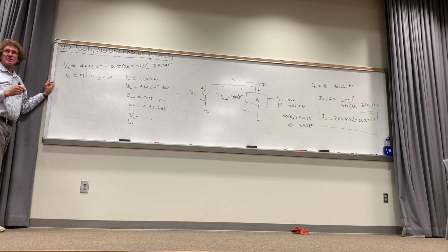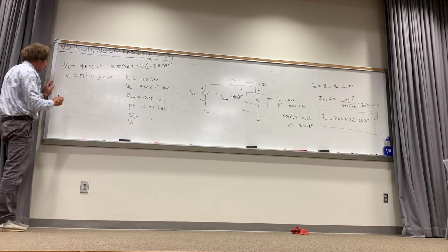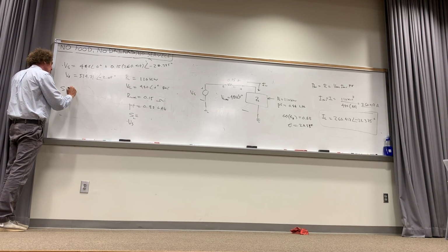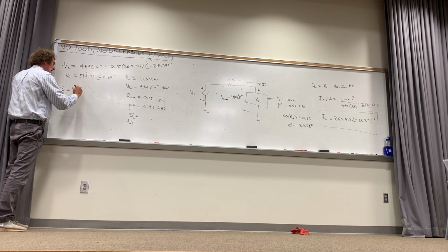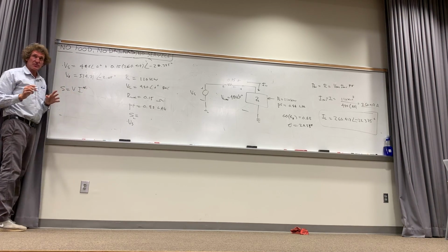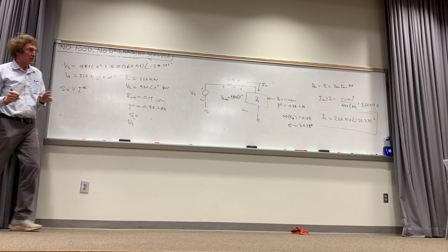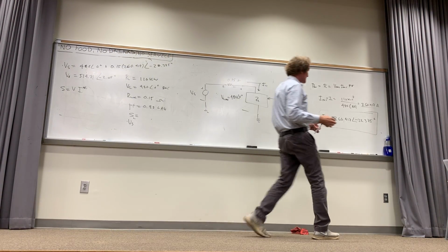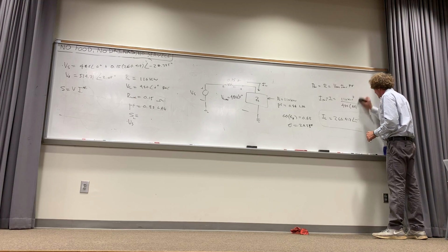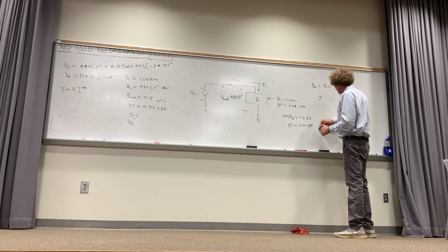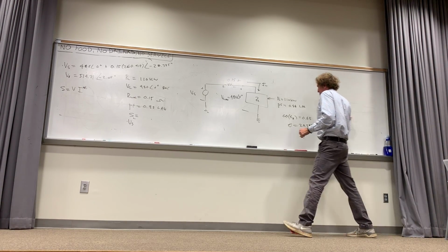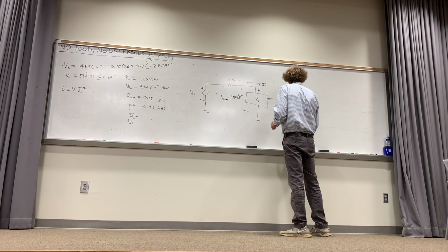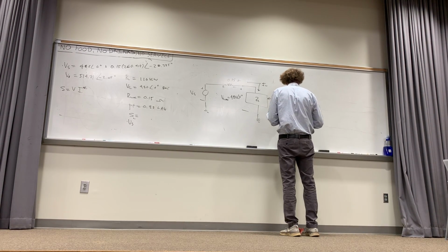Now, if we want complex power, we can do it a couple of ways. I want to first make sure everybody understands complex power. S is equal to V times I conjugated, right? That's what it is. When I look at complex power, I drew the power triangle, I drew it up last time a couple of times.